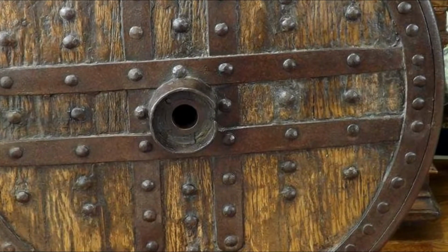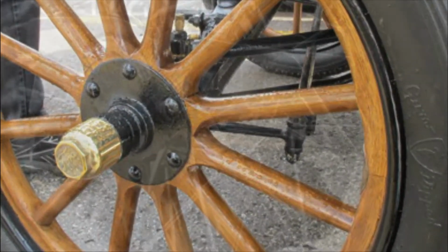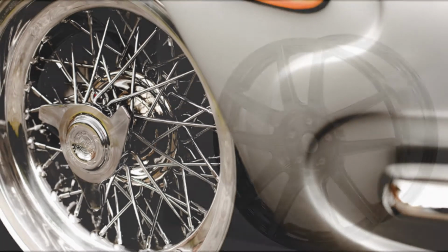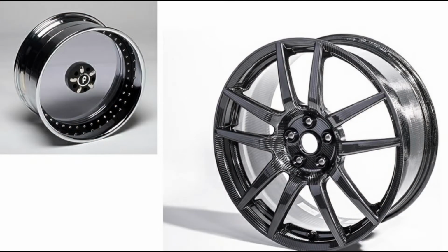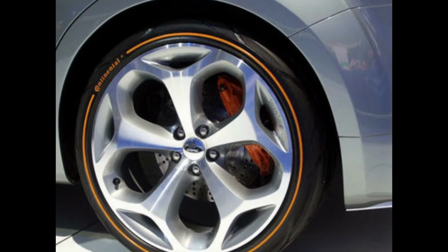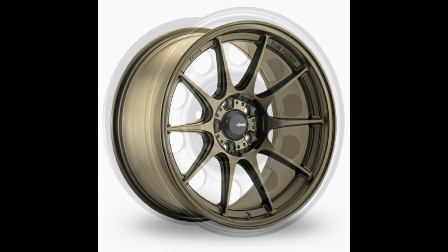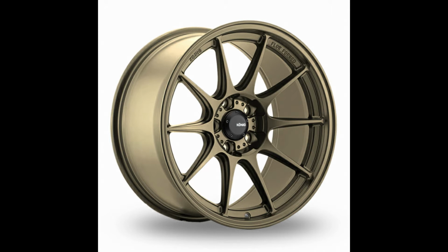As technology improved, new ways and materials were used to make wheels, and you can see some of this progress in the way car wheels are manufactured. Whilst in the past, both wooden wheels and wire-spoked wheels have been used on cars, and you can also find both carbon fibre and plastic wheels, most modern vehicles you're going to find either pressed steel wheels or aluminium alloy wheels. Steel wheels are easy to produce, they're relatively cheap, and they tend to be strong. But as a wheel building material, aluminium alloy does offer several advantages. And these include the lighter weight, better heat dissipation for the brakes, and the fact that they can actually be made to look a lot nicer, better aesthetics.